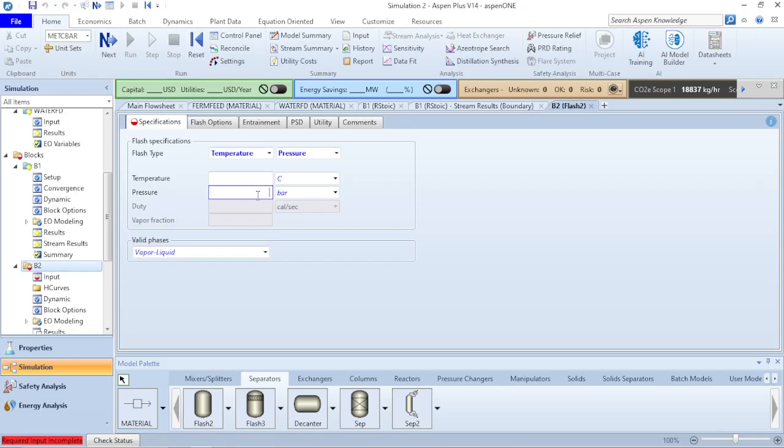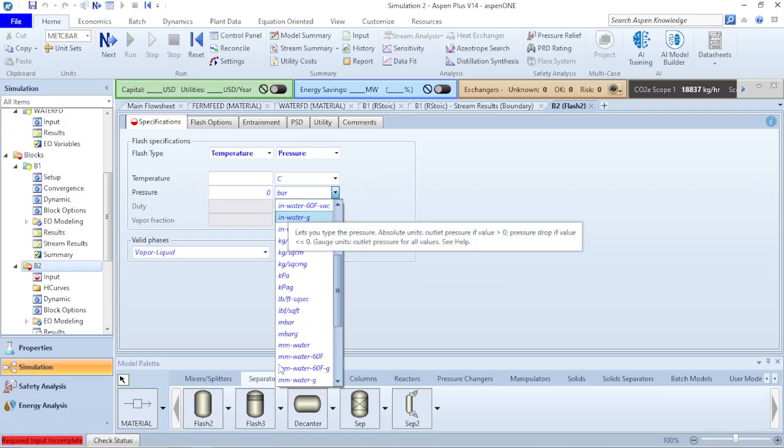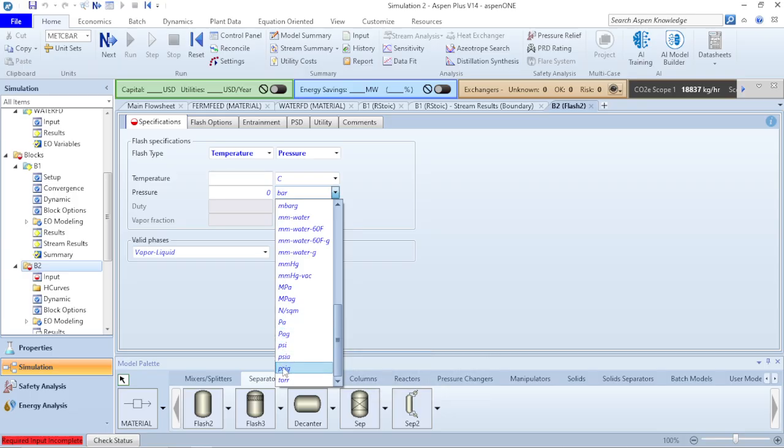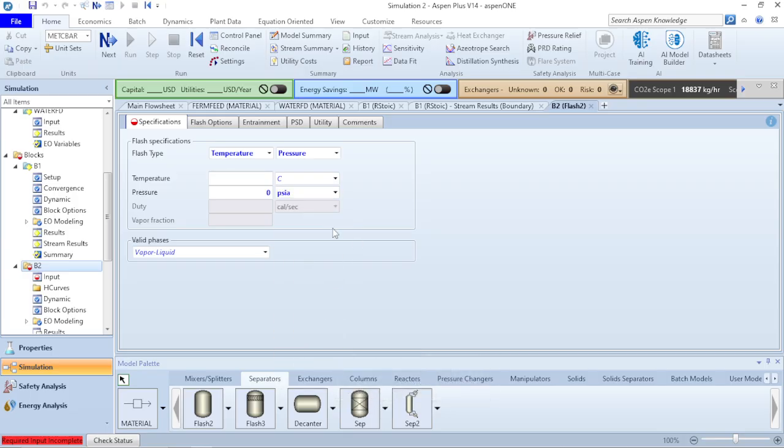Still have 0 pressure drop, we put in 0 here. Don't mind it. Anytime you put 0 in your pressure drop, it's just automatically specifying that it is 0 pressure drop. And then this was supposed to be working for 90 Fahrenheit. Let me confirm that. Yes, 90 Fahrenheit. Okay, let's add the pump to it and then we move on till the next video.